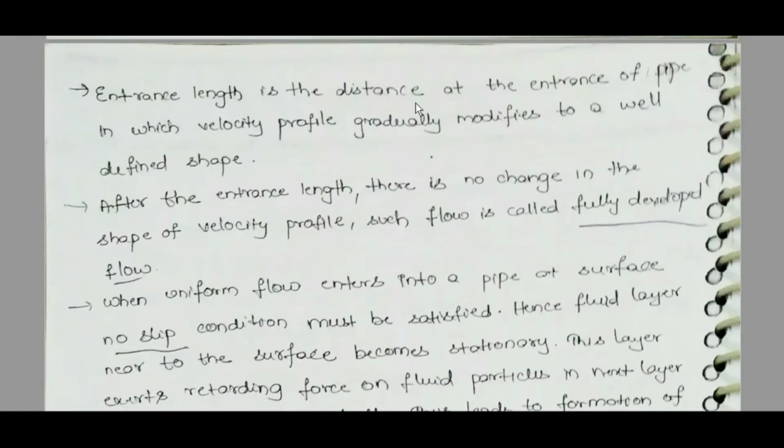Entrance length is the distance at the entrance of a pipe in which the velocity profile gradually modifies to a well-defined shape. After the entrance length there is no change in the shape of the velocity profile. Such flow is called a fully developed flow.